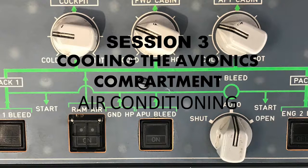Okay, so now what about the valves? We have a skin air inlet and an outlet valve. These are both installed in the fuselage skin at the forward lower left or right, so left and right hand side. So for your skin air inlet valve, that's located at the forward lower left hand side, and then your outlet is located on the right hand side. Okay, but they're both in the fuselage skin at the forward lower part. Okay, and the valves are electrically operated. They're the same type of valve, as far as configuration of it. They're both a single flap type.